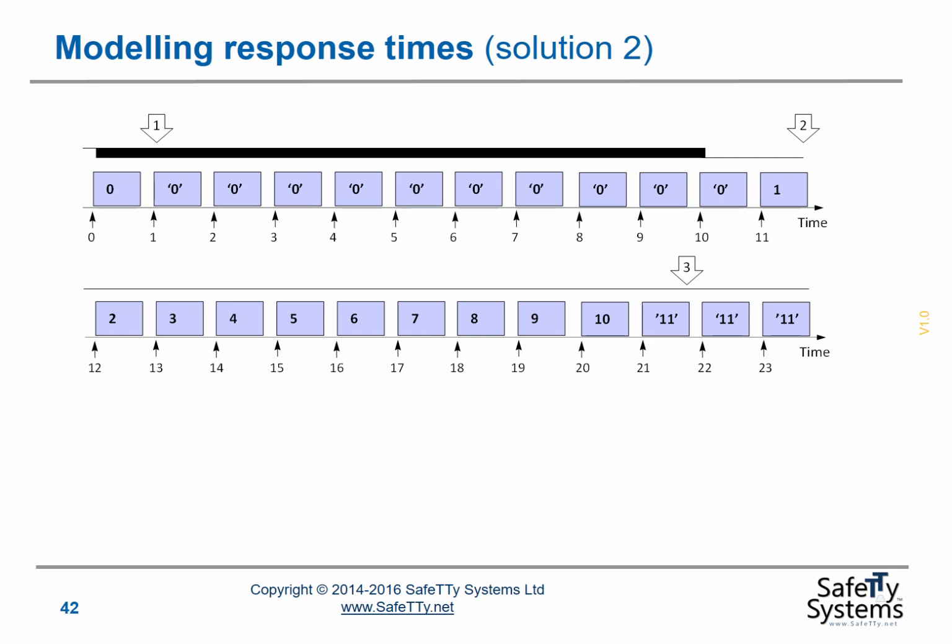What this indicates is that we assume the switch is pressed just after tick 0 at the left hand side of the diagram. Now we know that we may miss that tick reading in our task, so we have to assume that we only begin to detect that switch press in tick interval 1, which is indicated by the arrow 1 on the diagram.